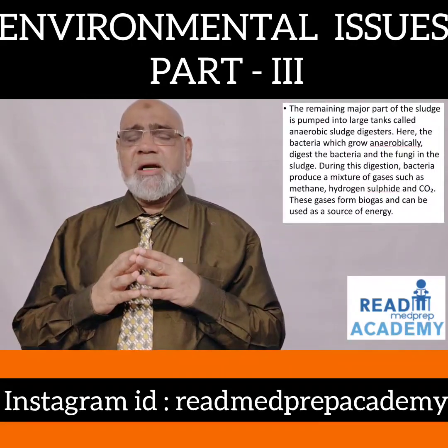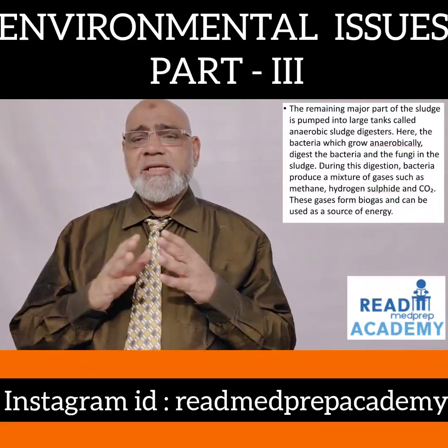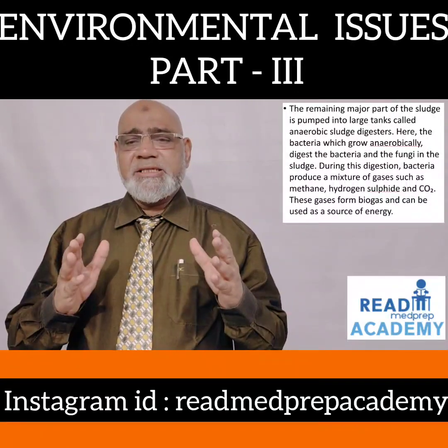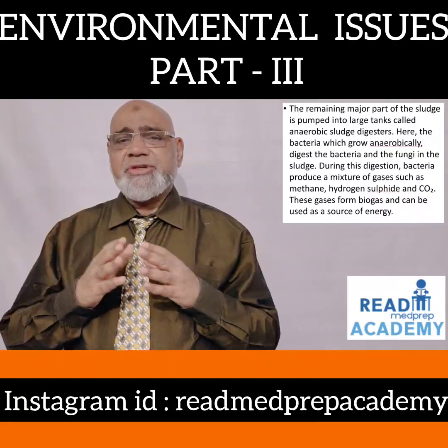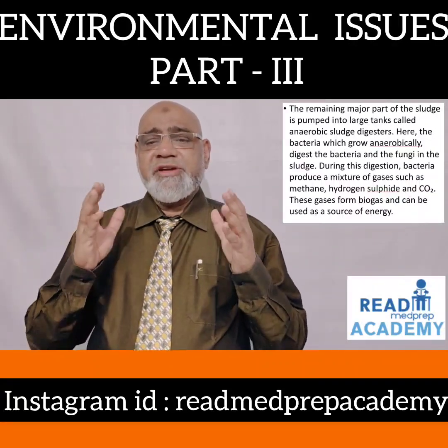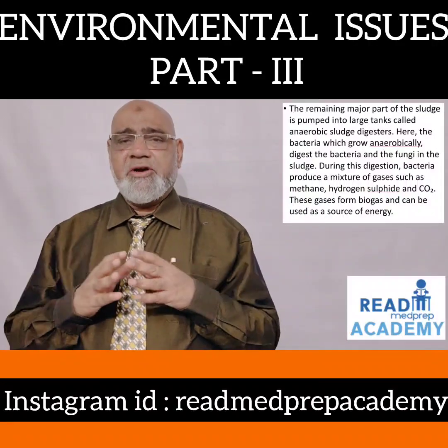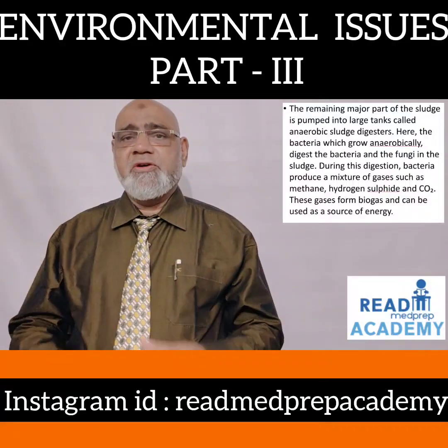The remaining major part of the sludge is pumped into large tanks called anaerobic sludge digesters. Here the bacteria which grow anaerobically digest the bacteria and the fungi in the sludge. During this digestion, bacteria produce a mixture of gases such as methane, hydrogen sulfide and carbon dioxide. These gases form the biogas and can be used as a source of energy.